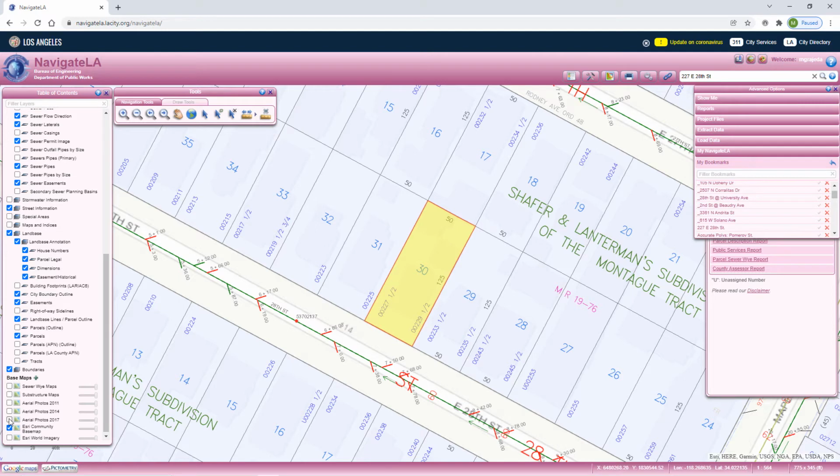With our layer settings established, we're now ready to create our theme. Click on the Save My Environment As option and select Theme as the environment type. Then, supply a name and description for your theme. As previously mentioned, the description is optional but recommended, as it functions as a tooltip whenever you hover over the theme name. Finally, press Save.